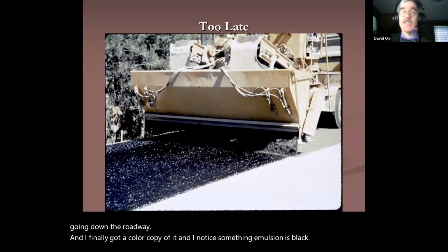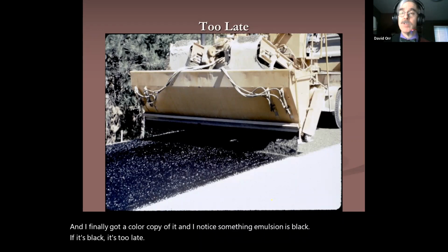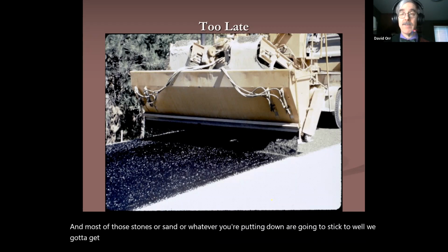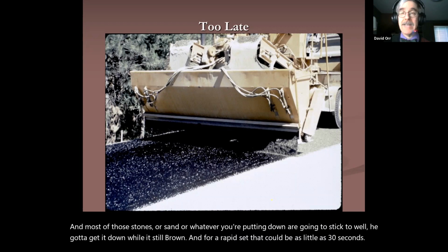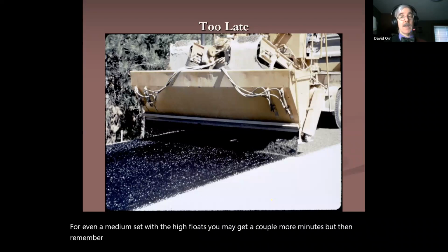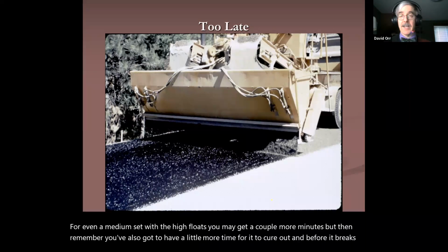If it's black, it's too late. And most of those stones or sand or whatever you're putting down aren't going to stick too well. So you've got to get it down while it's still brown. For a rapid set, that could be as little as 30 seconds. For even a medium set with the high floats, you may get a couple more minutes. But then remember, you've also got to have a little more time for it to cure out before it breaks for traffic. So be careful of that.